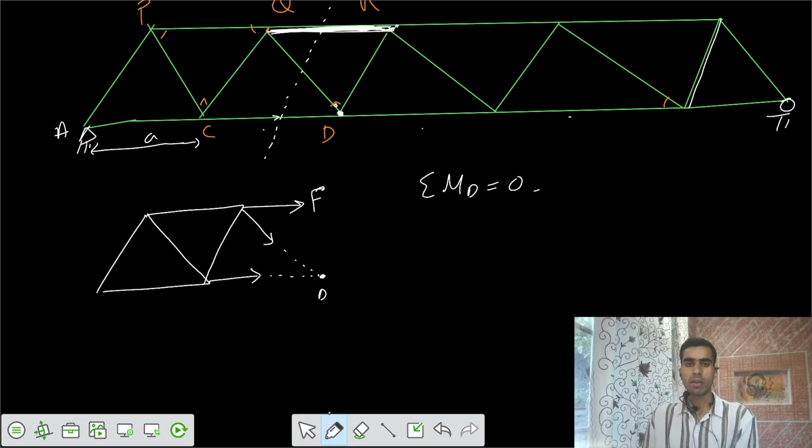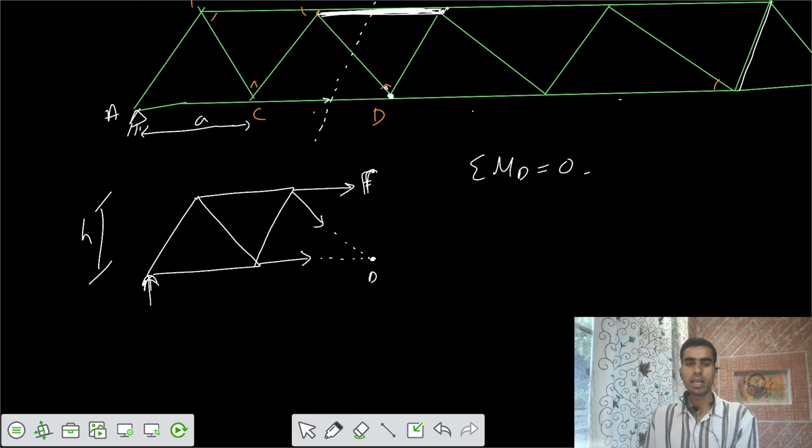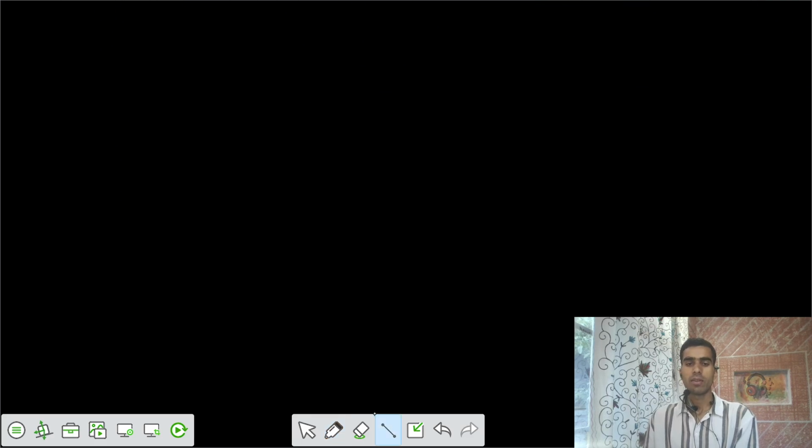And we have some unknown F at height H, and we have some reaction of RA. Now the load is placed at A. If the load is at A, the reaction at joint A is 1, such that finally F equals 0. So if I draw the ILD, the ordinate for the first point is 0.